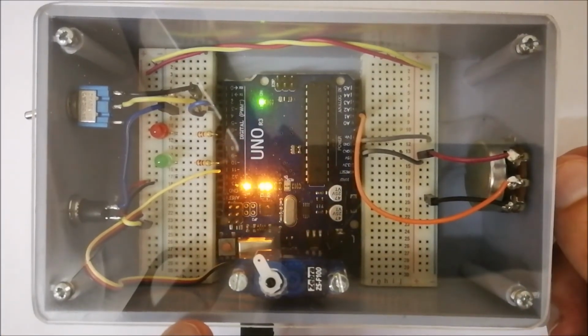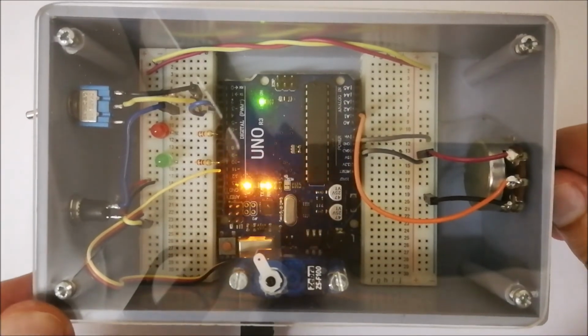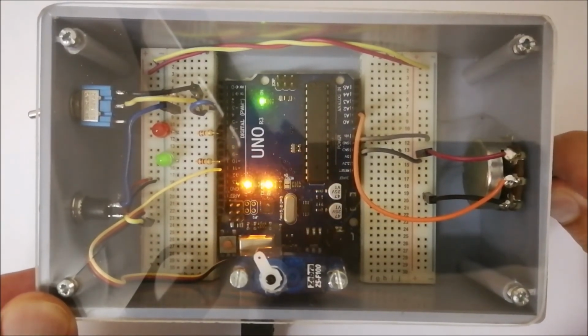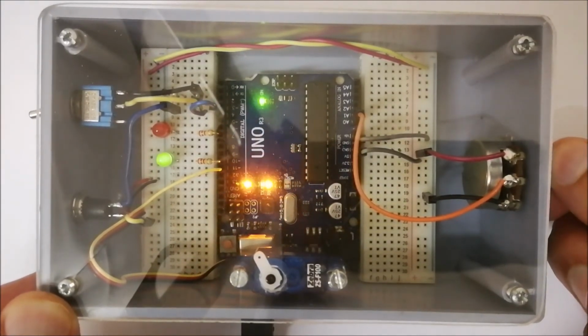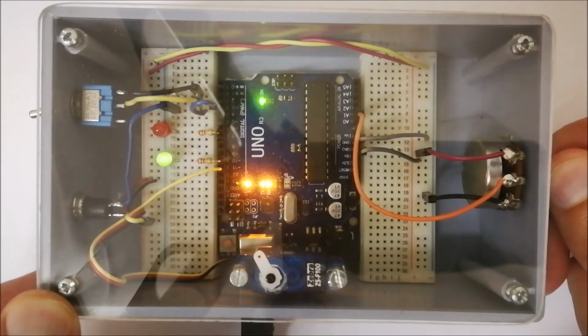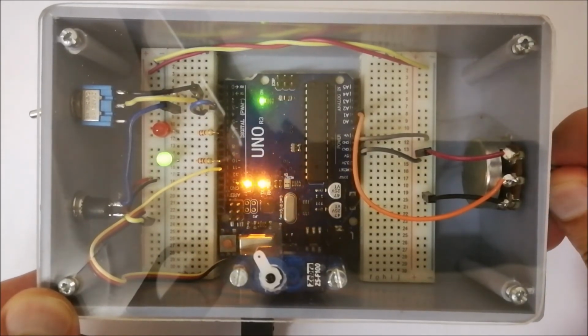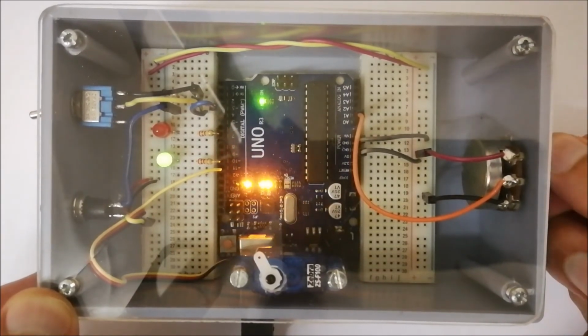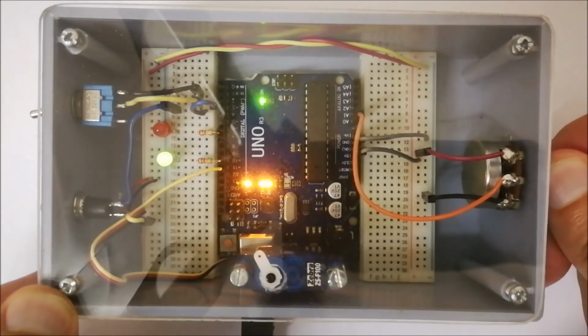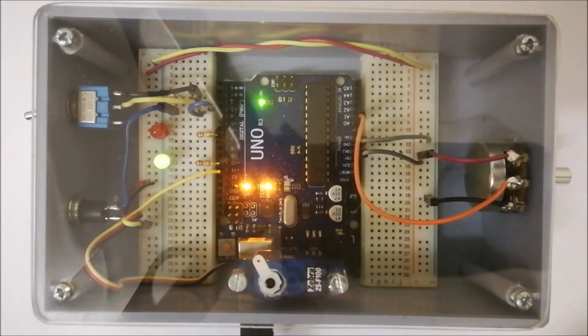I've turned down this variable resistor completely. It's time to increase it slowly. You'll see the LED does start increasing in brightness. It keeps on going, and as I'm turning this, it just gets brighter and brighter. And I'm turning it all the way right up to the end, and it hasn't gone dim again. So that divide by 4 that we've added into that line seems to solve this problem, allowing for up to 256 for the PWM output.